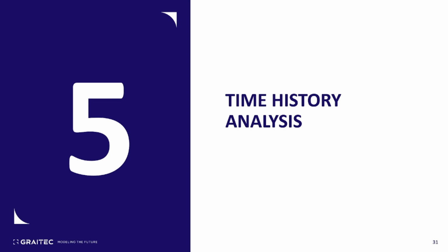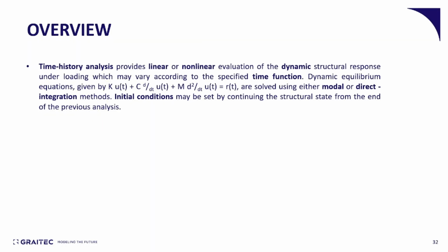Let's finish now with the last analysis we will discuss today, the time history analysis. A quick overview about this type of analysis. Time history analysis is a dynamic type of analysis that provides, if it is performed linearly or non-linearly, the evaluation of the structural response in a dynamic way under a certain load, which may vary according to the specified time function, as we will see later when defining the load.